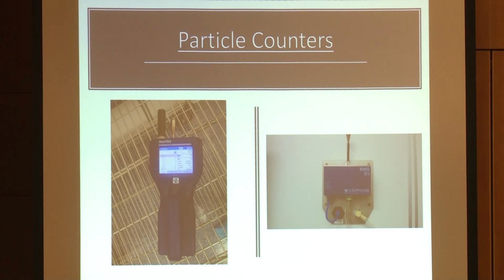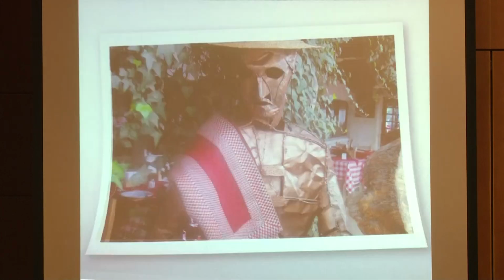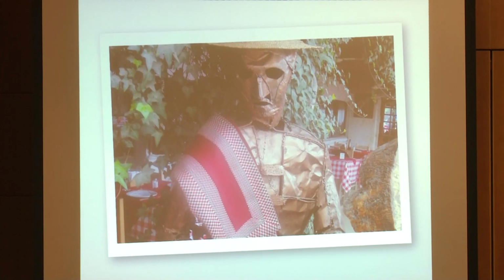And trust me, people look at those calibration reports. They are very important because that's what says that your readings are correct. So one of the biggest costs of a TAB company is the instrumentation, because if you have X amount of TAB technicians, you're going to have X amount of sets of TAB equipment, devices, and test instruments.